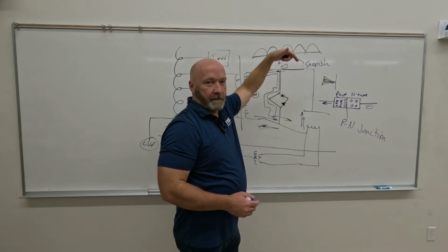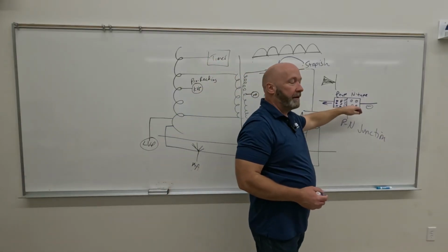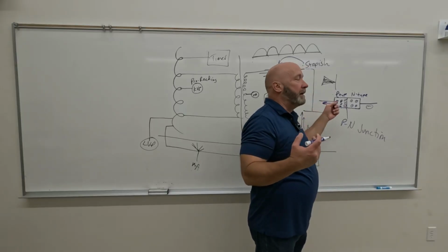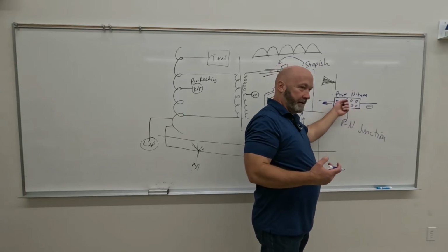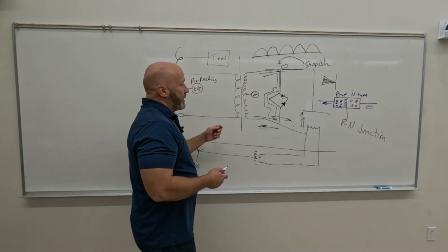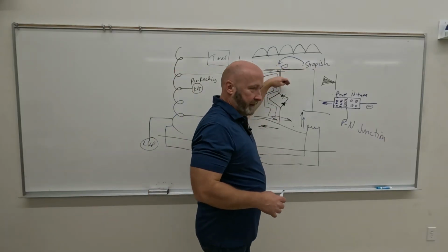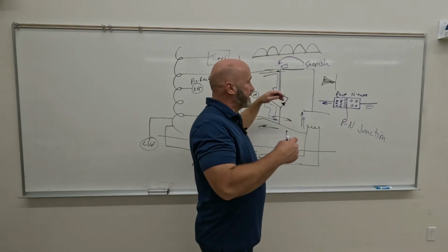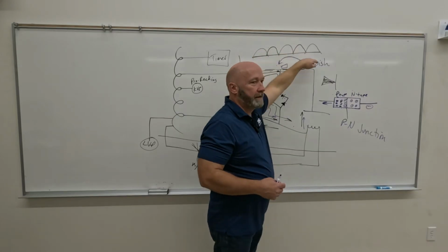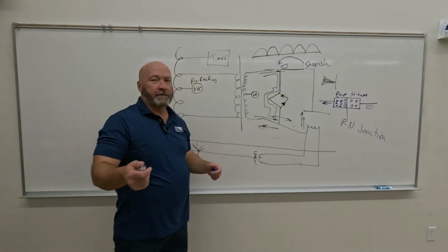Okay? So what's the takeaway from this? These are our rectifiers. If you apply a negative charge to the p-type, no flow of electrons. If you apply it to the n-type, then you've got flow. Okay? In that way, if we use 4 of them, we can not just stop the electron flow, we can stop it from going to the anode and also invert it so that we can use the full wave. Okay, we're full of things today that actually make sense in X-ray.